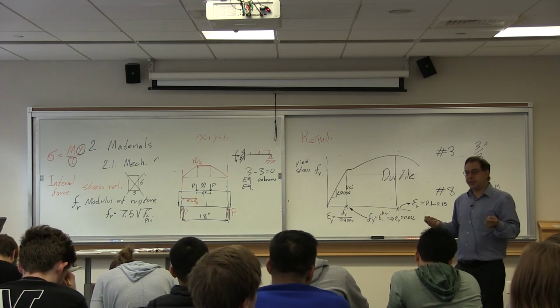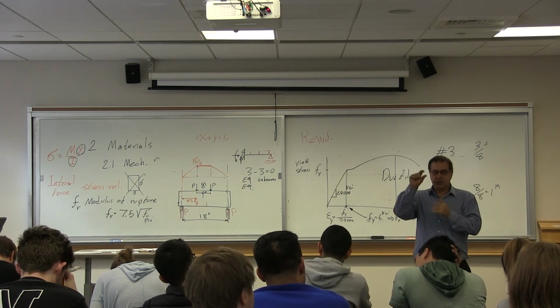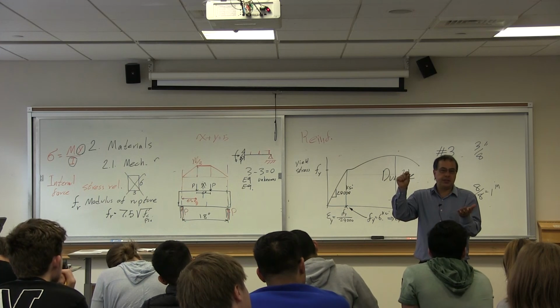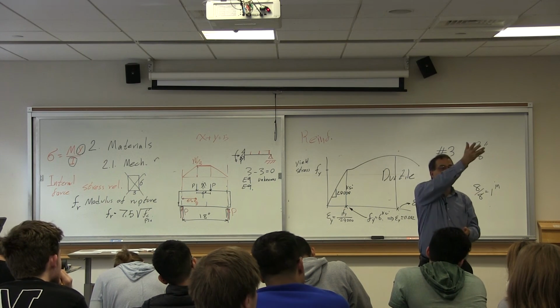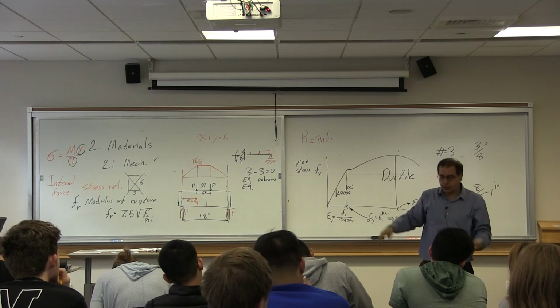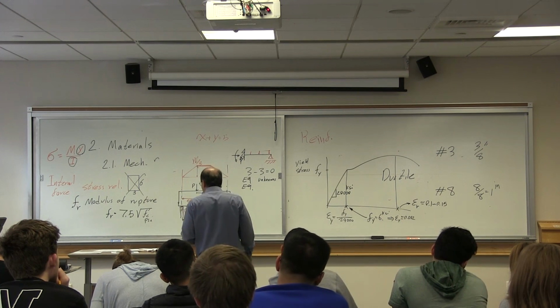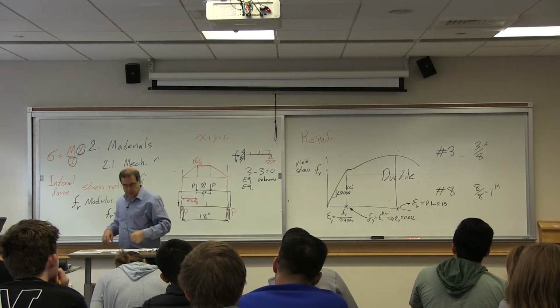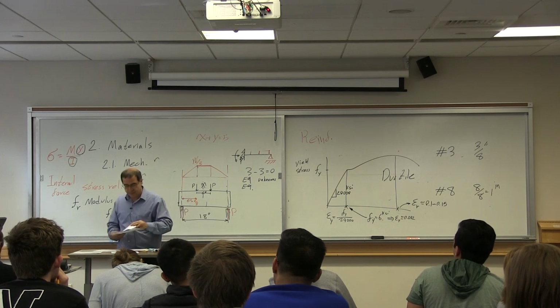It can give you warnings if things want to fail. If an element is deforming very little, you cannot notice, you don't see anything. But if you have a beam that is sagging 1 foot, you know something is wrong here, right? So that's why we want to have a ductile behavior. Let's just stop here. We reconvene in 12 minutes or so.